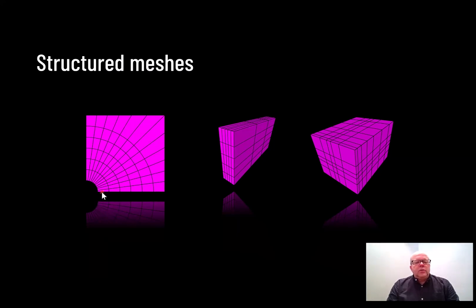So I can go 3 columns to the right and 3 rows up, and I can find this element here. You can set the density of the mesh by specifying the points on the line here. So I can say that I want more elements here or here, and then the algorithm can generate more elements there.